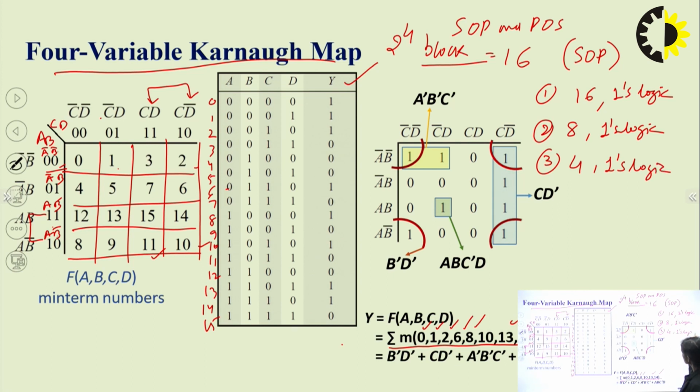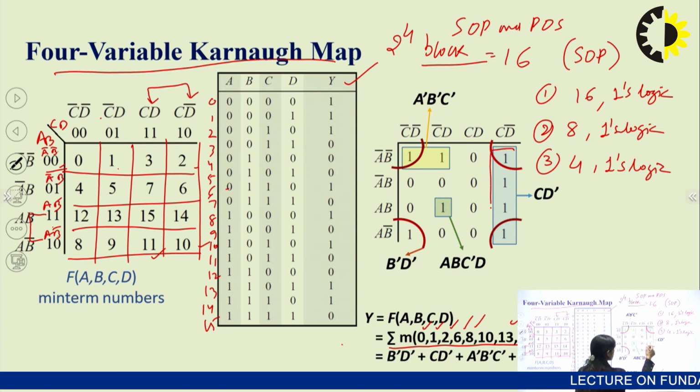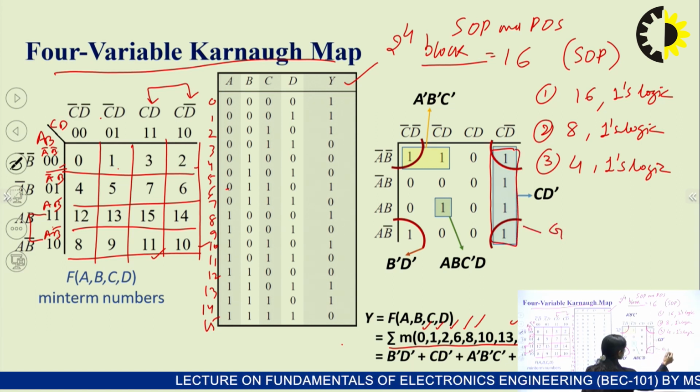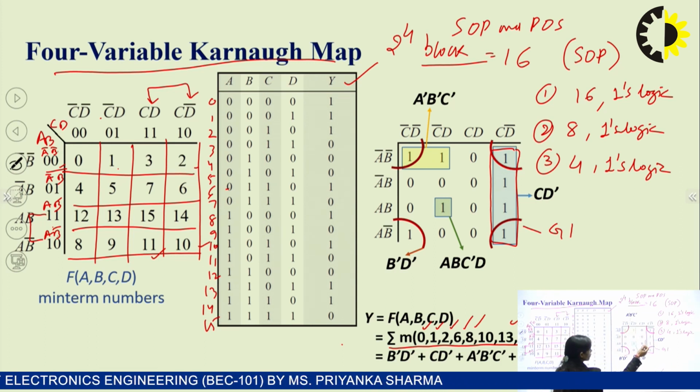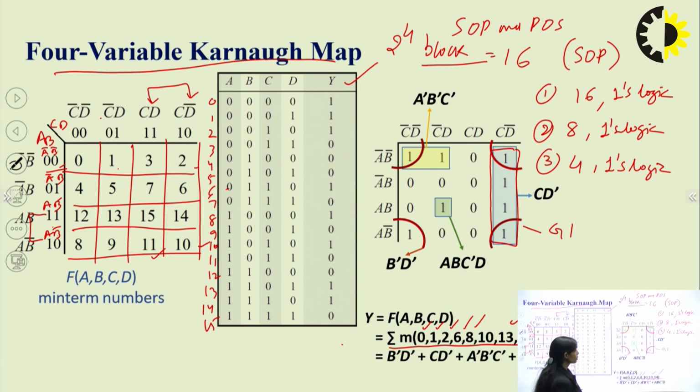So this is coming here, either it is vertical, any adjacent groups, any adjacent logic pairs we can take. So we have ones here. So this forms one group. This is called group 1. I am taking this as group 1. And after this we don't have any other four. We have other fours. We can also take the corners 1 logic. So we can take the corners 1 logic we have taken here. So this is forming the group 2.